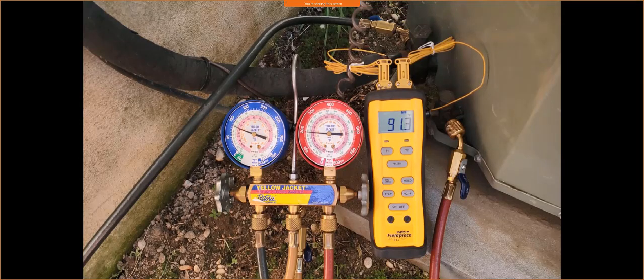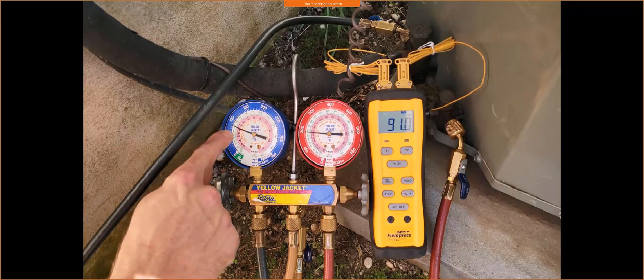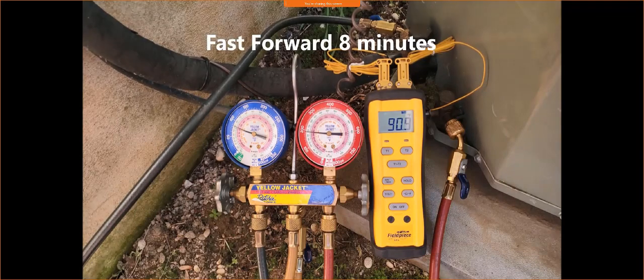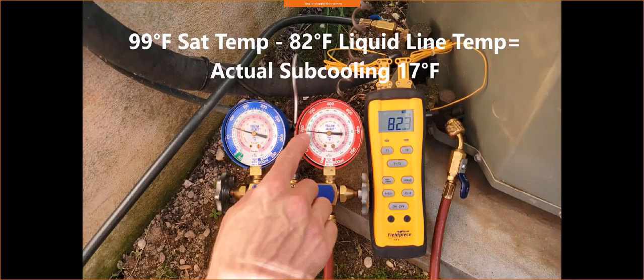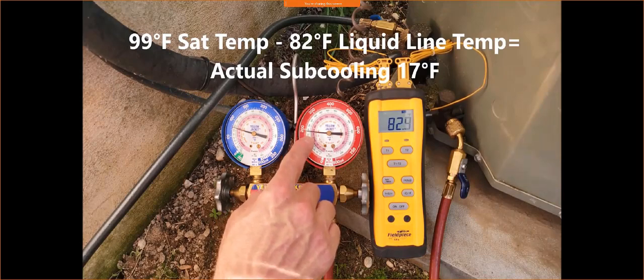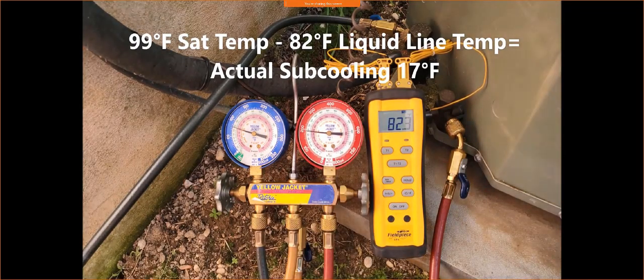When that indoor heat load is high, your saturated temperature and your pressure on your vapor side will be a little higher. So now we're checking the subcooling, and we see that we have 99 degrees as a saturated temperature, 99 minus 82, and you see that we have 17 degrees of subcooling.